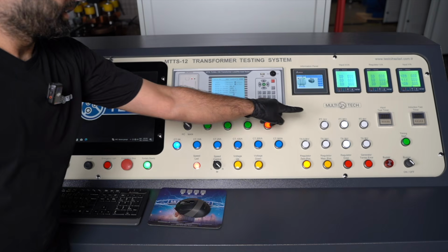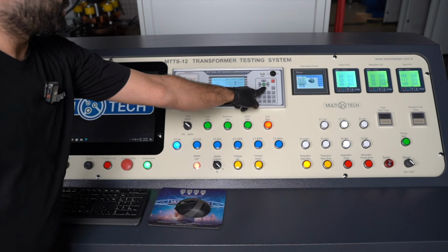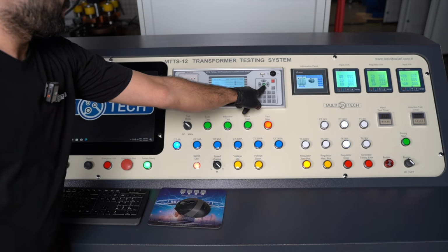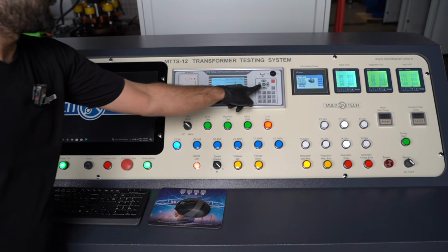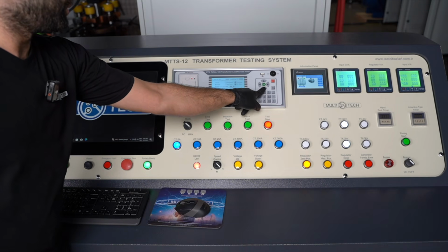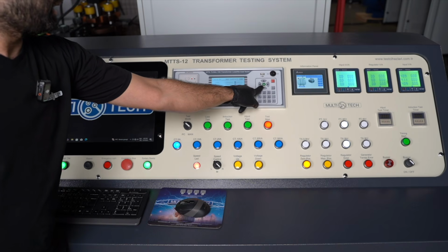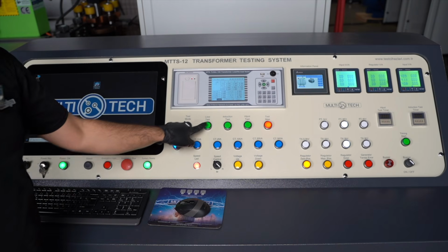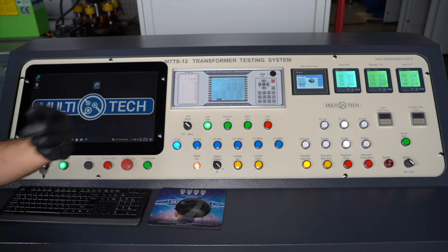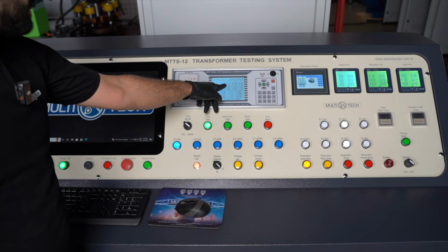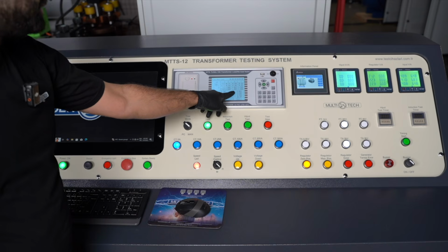Since I selected the PT range as 3 kV, I enter 30 volts, and since I selected the CT range as 5 amperes, I enter 5 amperes. Then I press the begin button to start the test. On the power analyzer screen during the load loss test, we display the voltages, currents, and losses.